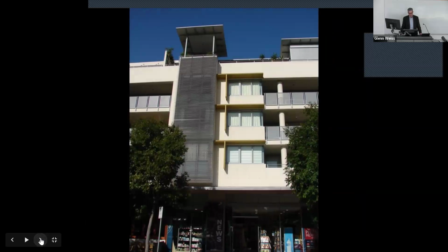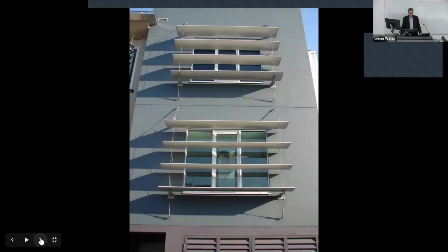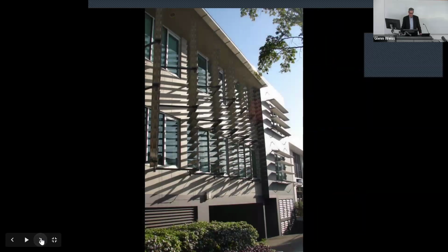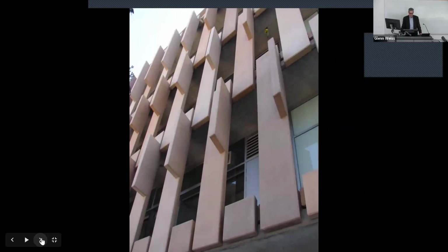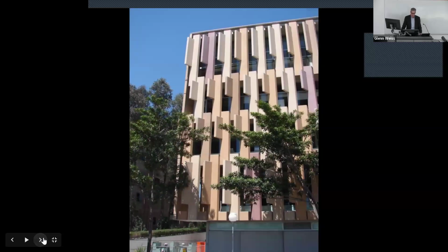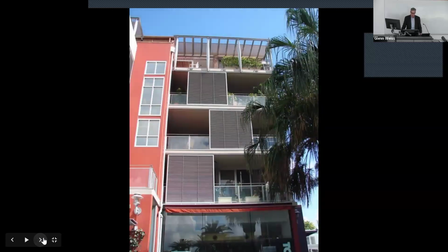You can see the horizontal wooden screen coming down in front of the windows, and then the funny T-shaped shade forms. Giant blinds, you might say. Smaller versions, but still large. Architectural detail made entirely to help block the sun. This is probably an east and west facade rather than a northern facade. Here you see them, because you don't have to 100% protect everything in the building in order to help with the situation.